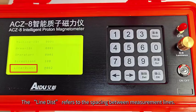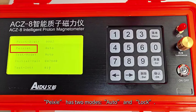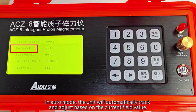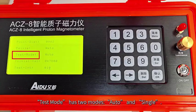The line dist refers to the spacing between measurement lines. The point dist refers to the spacing between measurement points along the same line. PIXI has two modes, auto and lock. You can switch between auto and lock by pressing the number 0 key. In auto mode, the unit will automatically track and adjust based on the current field value. Lock mode is primarily used in cases with large geomagnetic gradient changes, allowing for manual tuning to achieve more consistent readings.